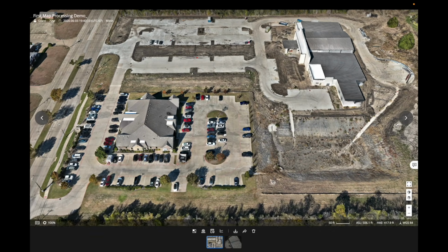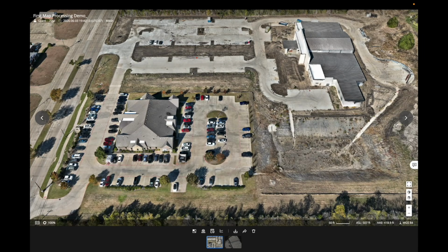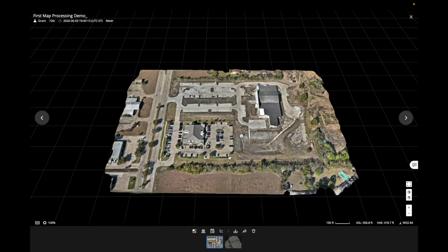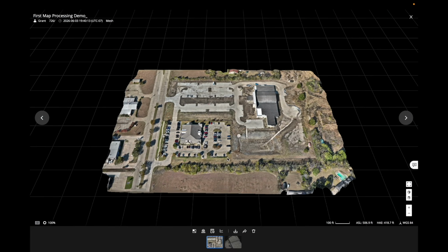For example, the 3D map can help teams review site conditions, understand terrain and structure context, support future flight planning, and create project annotations based on the latest reconstructed data. For this walkthrough, I'll keep the focus on reviewing the completed 3D model and then using Analyzer for measurements, annotations, and sharing. This review step is important because before sharing the model with the rest of the team, we want to make sure the result is actually useful and ready for review.